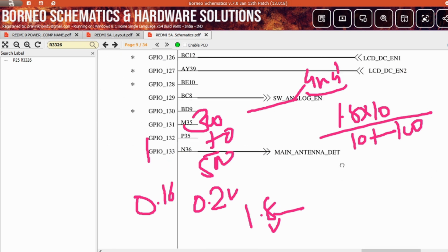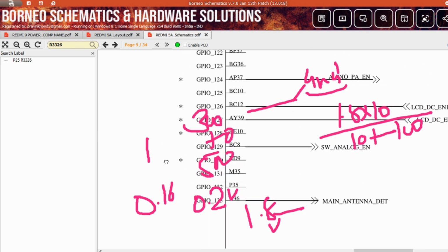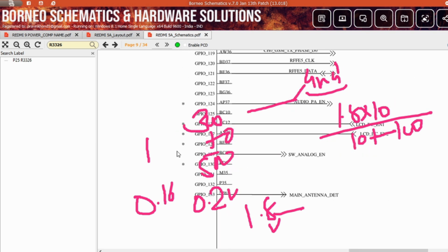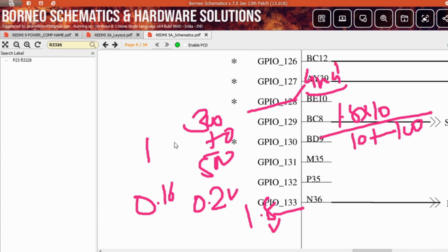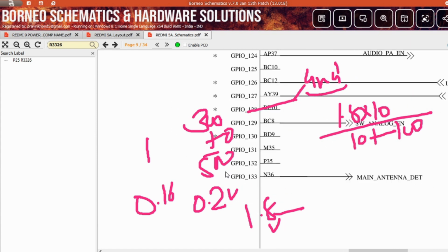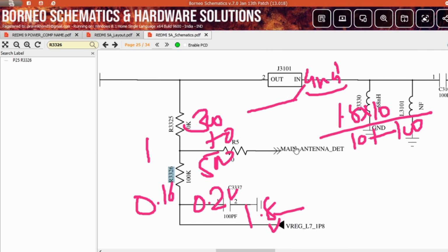Just click this line. Now this line goes to the GPIO section in the CPU, general purpose input output. I've already told you in previous videos, every IC has many sections according to the sequence, like controlling section, voltage input section, output section. So the CPU has many sections. Now one section is called GPIO, general purpose input output section, right? Now the main antenna connection line is connected to the GPIO section of our master IC, the CPU, right?